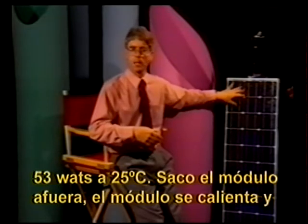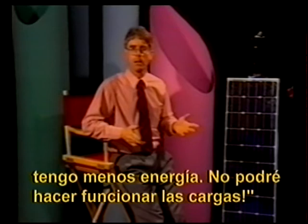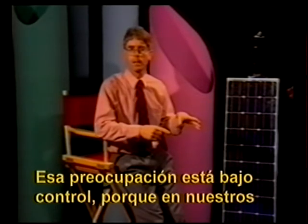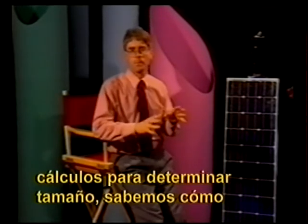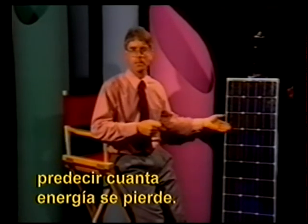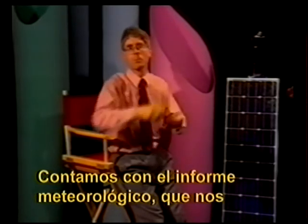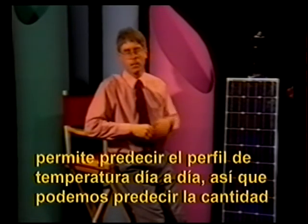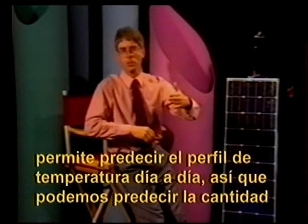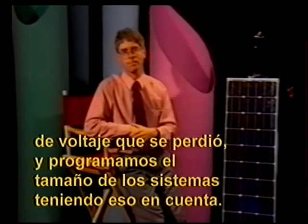Now I'm going to take this module, put it outdoors, it's going to get hot. I'm not going to have as much power. I'm not going to be able to run my loads. That concern is handled because in our sizing calculations, we know how to predict how much power is lost. We have weather data that allows us to predict what the temperature profile is going to be day by day. So we can predict the amount of voltage loss, and we size our systems to take that into account.